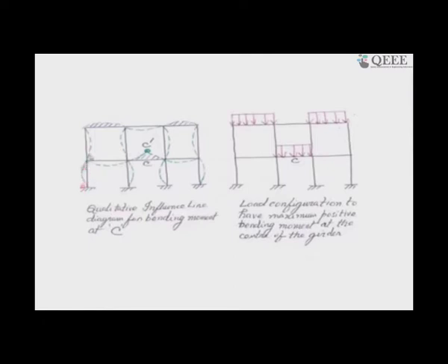And we are actually having a diagram for all the portions of the frame like this. If so, you can easily identify, we say it's the sagging moment effect, because the moment you apply the unit load in the sagging direction, if this is positive, this will also be positive, this will also be positive.